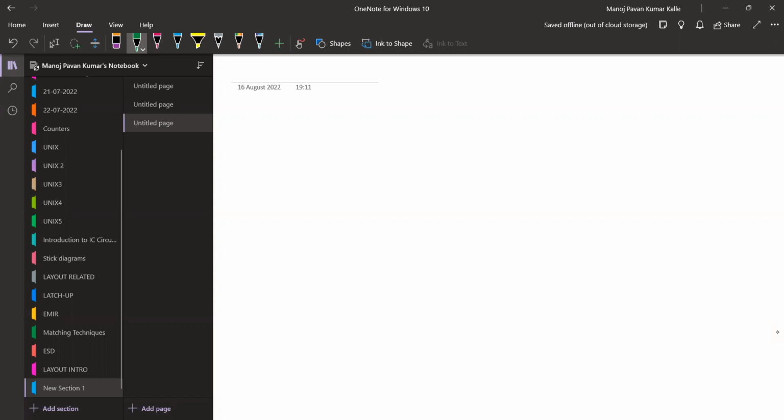No, see, don't think like that. The entire industry is not working only on FinFETs, because there are so many companies working on even higher nodes compared to 45. FinFETs are usually used for lower voltage applications only. But once you are dealing with higher voltages, FinFET won't support that much voltage, and you have to go to higher nodes only.